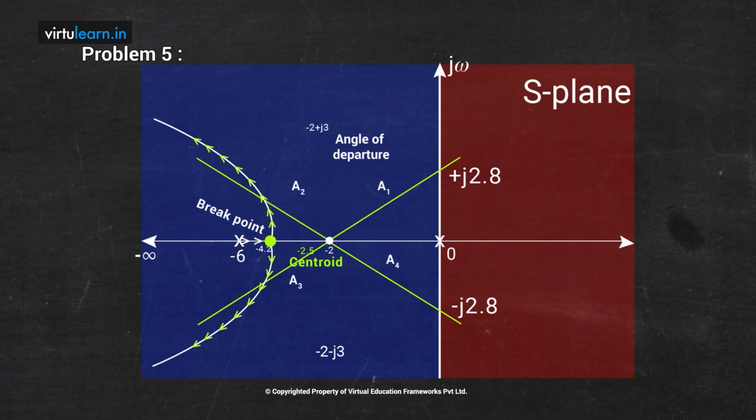We have an angle of around 70 degrees, so it takes the 70 degrees and goes to infinity. It crosses the imaginary axis. While crossing, it takes the imaginary crossover point, and the bottom one also takes the imaginary crossover point. It goes like this. Now both real-axis poles are coming together, and one goes towards the left direction, whereas the complex poles go towards the right direction, and these two are responsible for the unstable nature of the system.